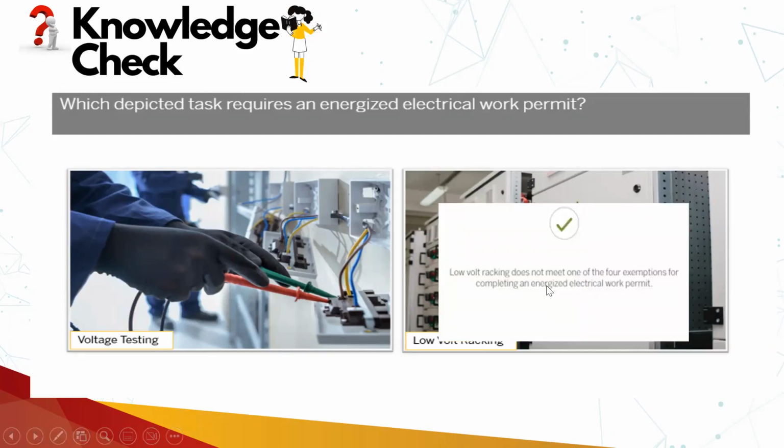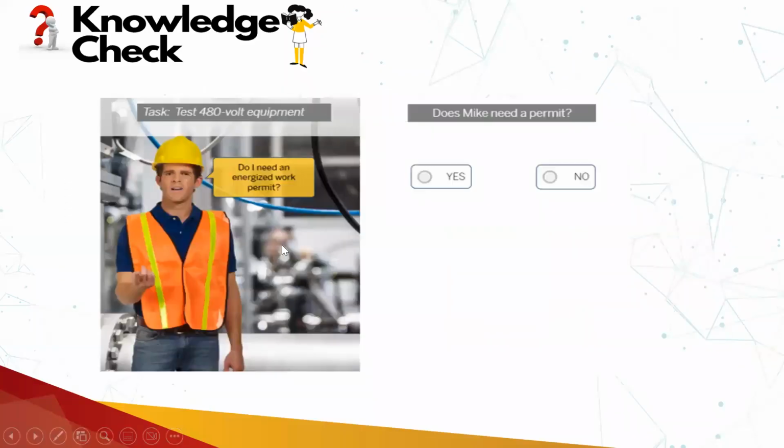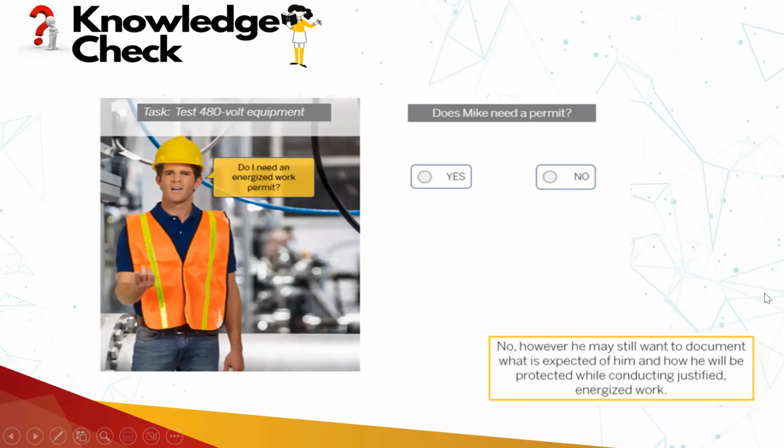So low voltage does not meet the 4 exemptions for completing an energized electric work permit. So this task will require an energized electric work permit. Do I need an energized electric work permit? Testing of 400 volts test equipment. For testing, an energized electric work permit is exempted, so it's not required. However, he may still want to document what is expected of him and how he will protect himself while conducting that justified energized work.